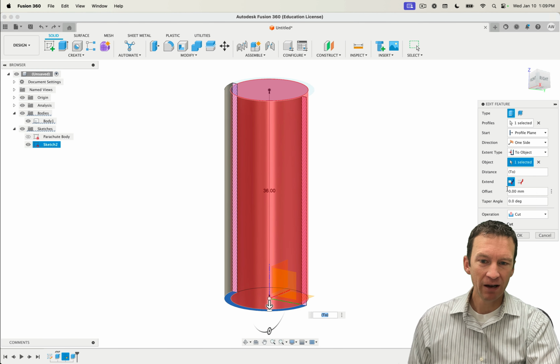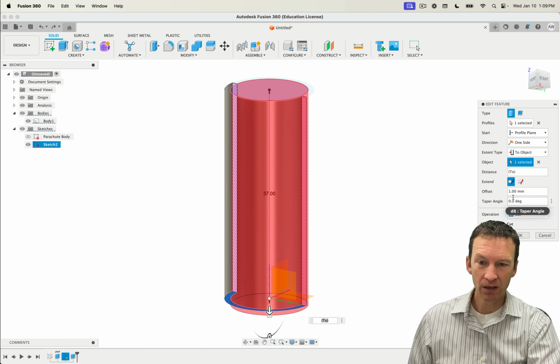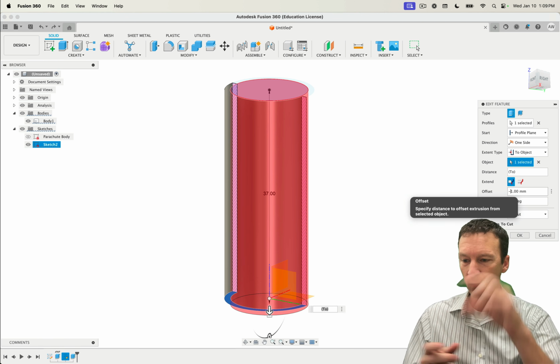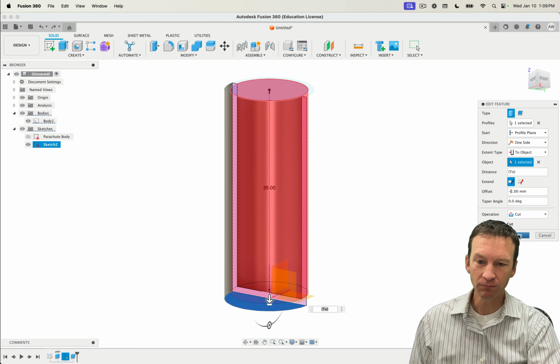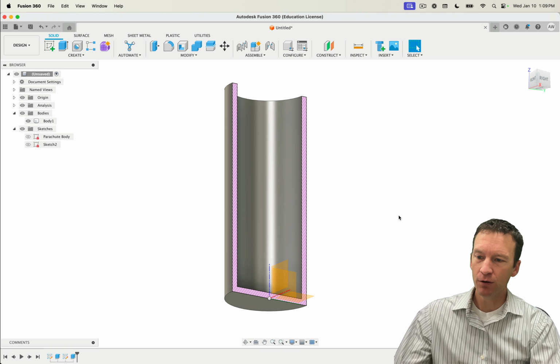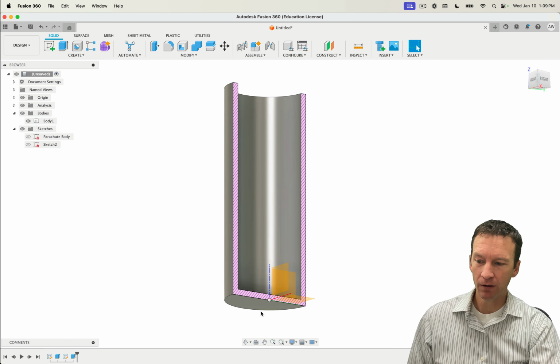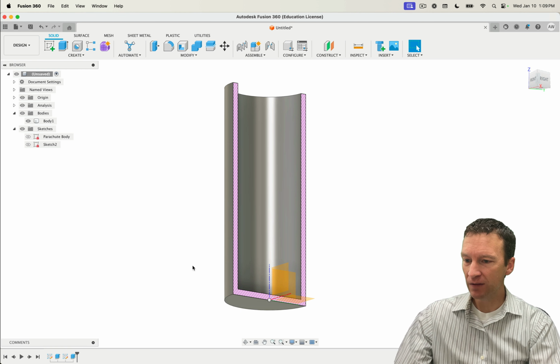which is fine, but now I have this offset value. So I can set the offset to 1 millimeter, negative 1 millimeter, or however thick I want that bottom piece to be, right? Perfect. So now the cut is dynamic. And so it's going to automatically cut down to the very bottom and then subtract 1 millimeter. So now the benefit is, I'm going to leave this on section view.